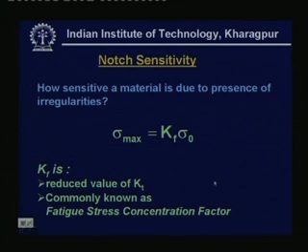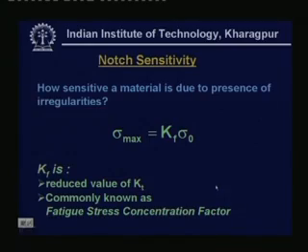That is what I was trying to tell you precisely, that Kt was a theoretical stress concentration factor, there was no consideration of the material in use. Now, when we consider the Kf, then we ask whether the total Kt is applicable to this typical material or what is the situation. So, in this particular case the notch sensitivity has come into picture.